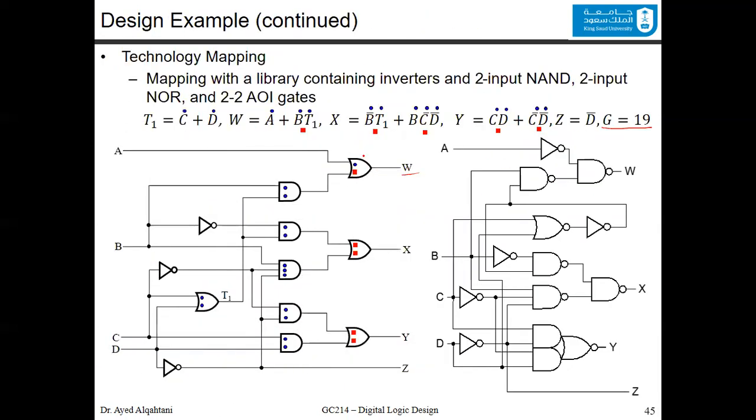You can notice that the OR, we replace it by NAND. Some of the ANDs here, we replace with NANDs. This one has been replaced in another circuit, and so on. So you can have the function, and this also tells us that you can draw the block diagram for a certain function in so many different ways.